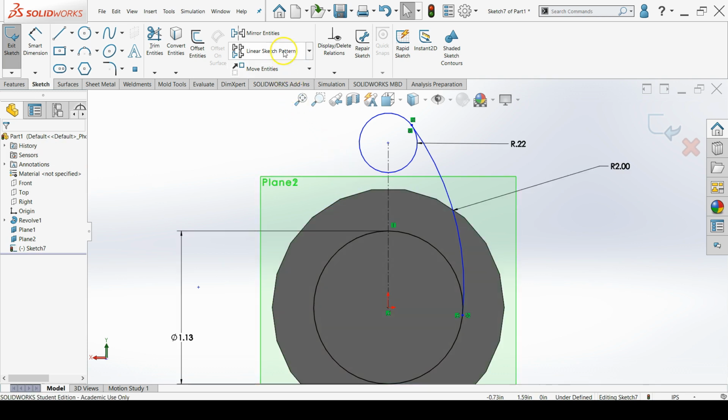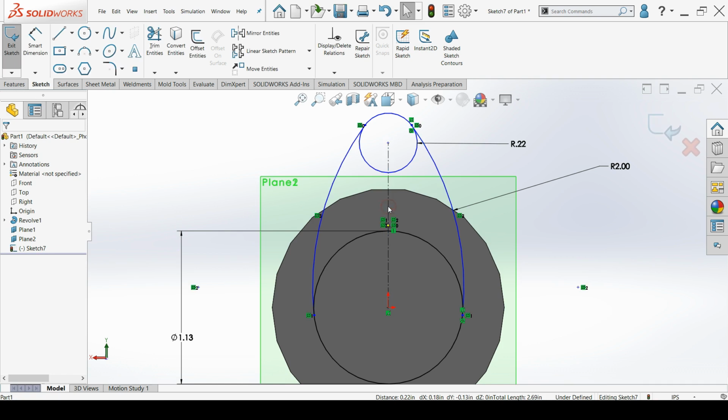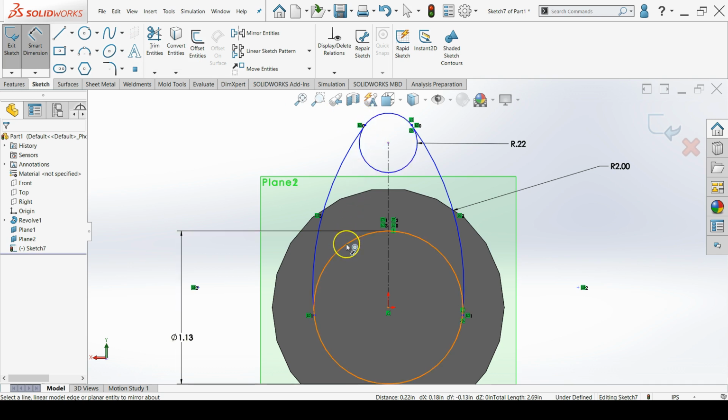You can then mirror the arc to the other side using the vertical center line. To get the 1.468 dimension to go to the maximum arc distances, you will have to select a dimension, switch to the Leaders tab of the Property Manager, scroll down to the bottom, and switch both the first and second arc conditions to max.